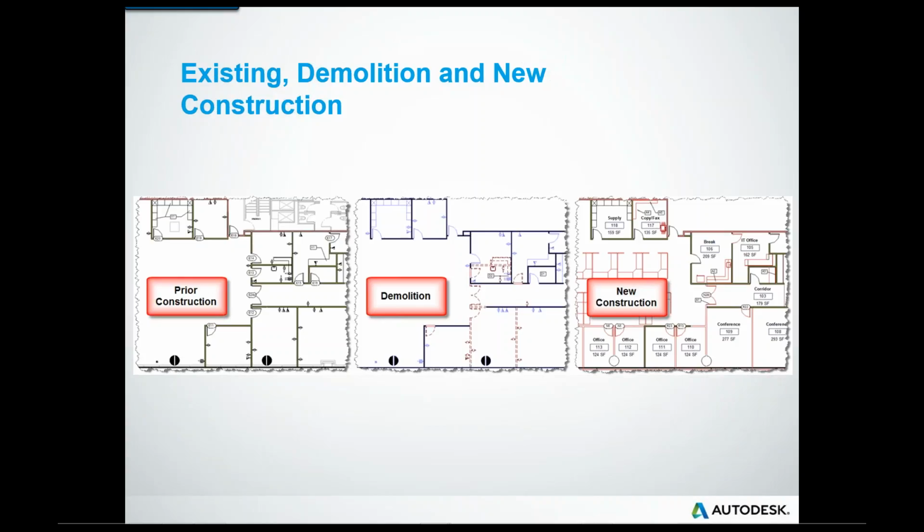And the prior construction, for example, a lot of times I see prior construction and demolition phase as AutoCAD backgrounds. And quite frankly, it makes it simpler to distinguish between the two. And then our new construction can be all in Revit. So a lot of times, the firms that I work with have AutoCAD backgrounds, and we use those AutoCAD backgrounds as prior or existing and demolition.